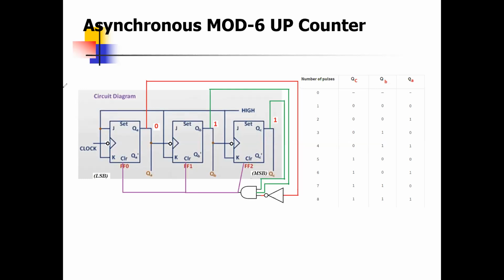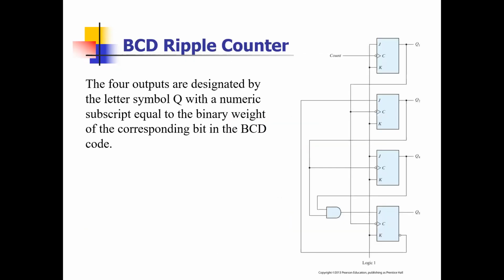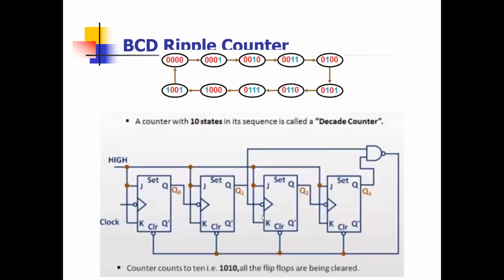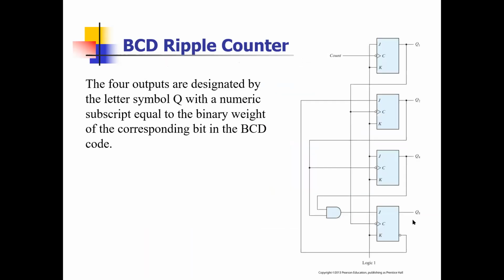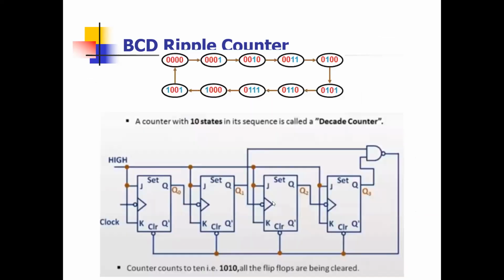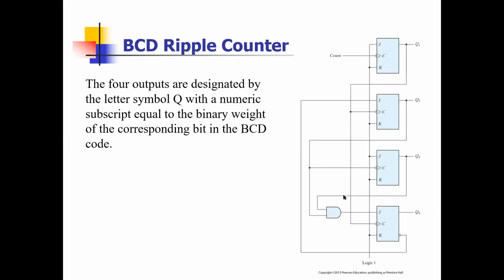Anyone has question? No, clear. Okay, so this is BCD ripple counter design with JK. I explain you here also with JK. This is a good circuit. So try to use this circuit with 1. Don't use this. This circuit they design in the book with JK. So you can design in this form also, but I prefer to use the simplest way. Connect J and K with 1 and then do this. This will be easy. No need to do this.